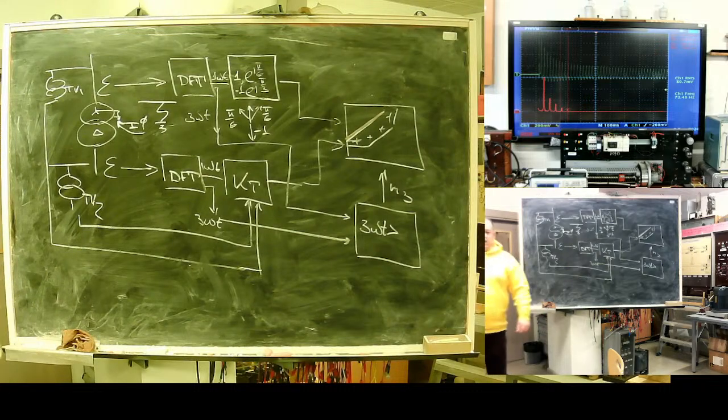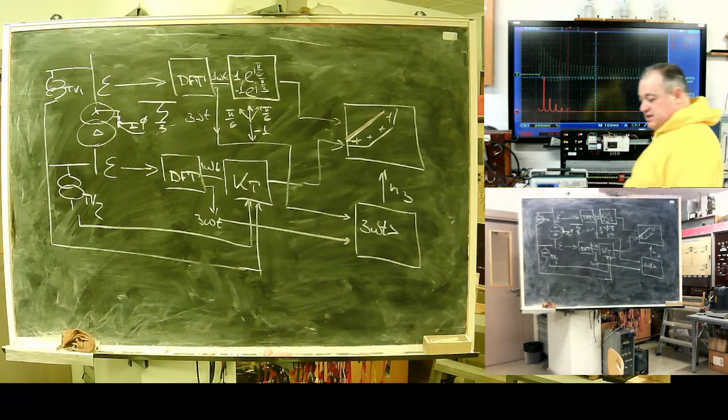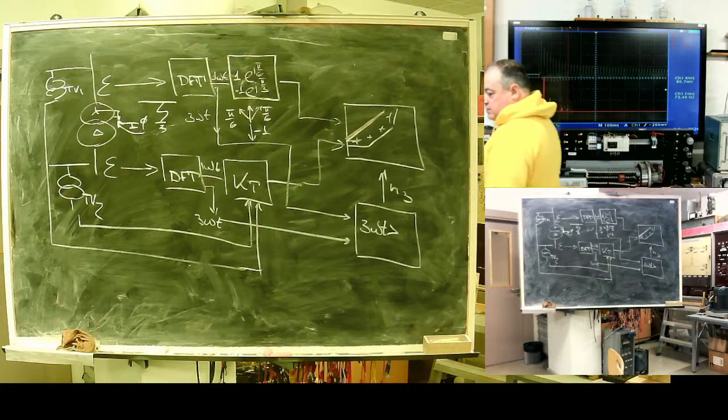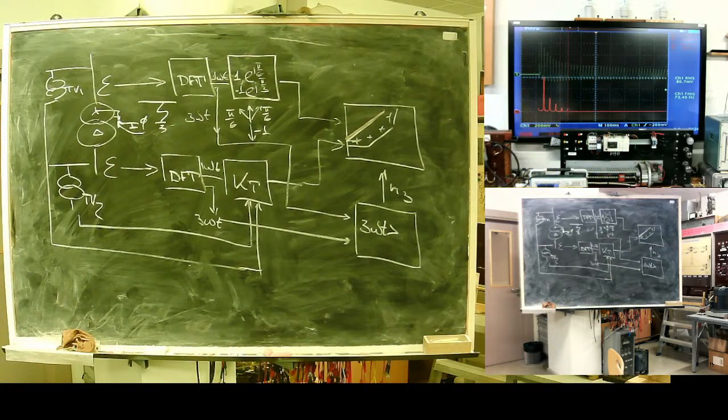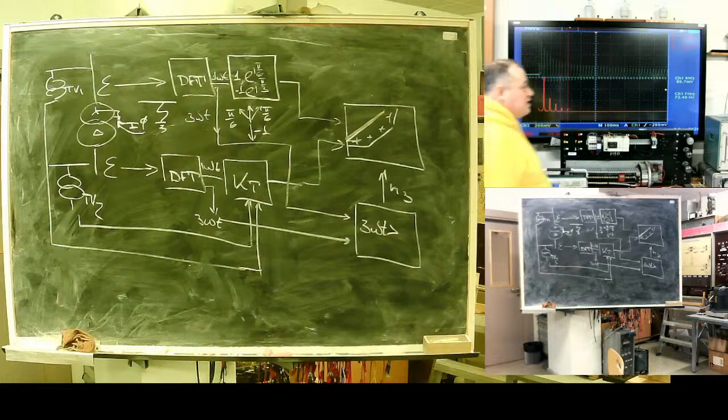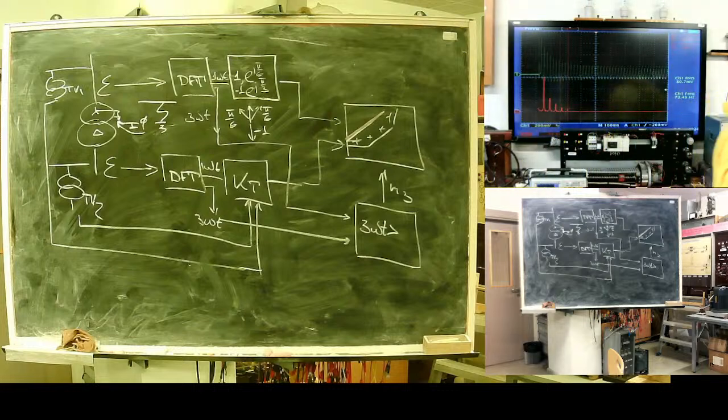The schematic with offset transformer is immune to this because delta connected current transformers protect the relay from zero sequence currents. Here, zero sequence current from an absolutely outside fault may cause misoperation.